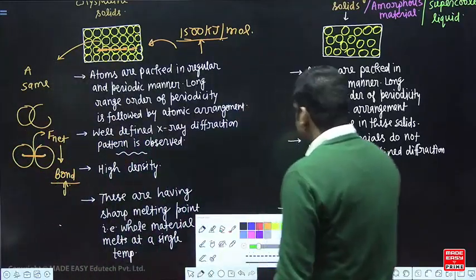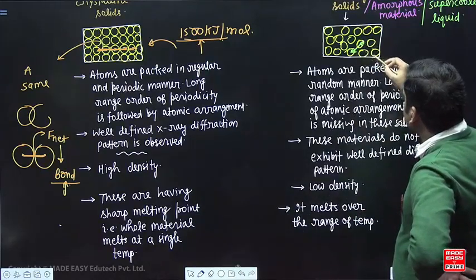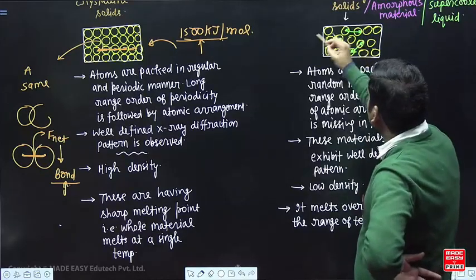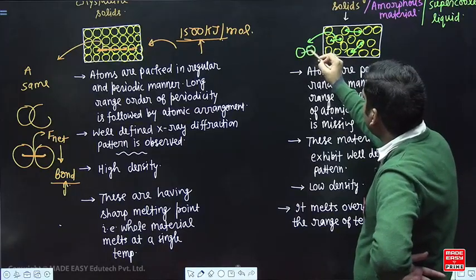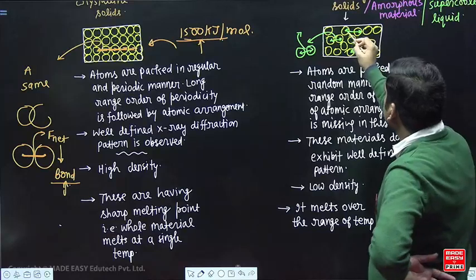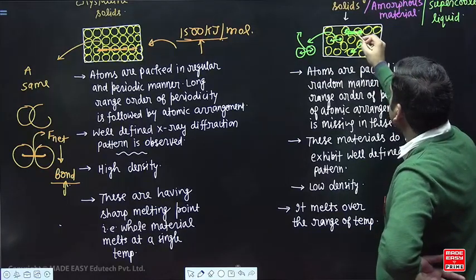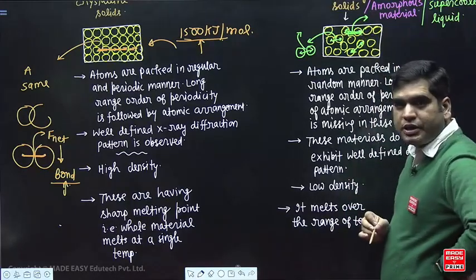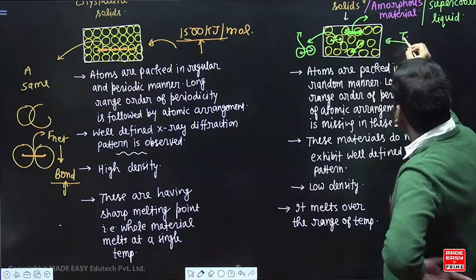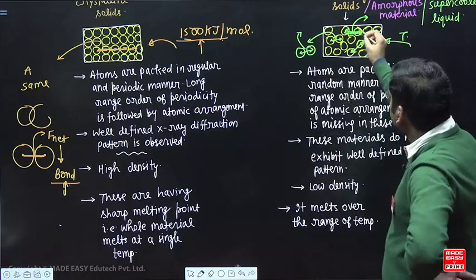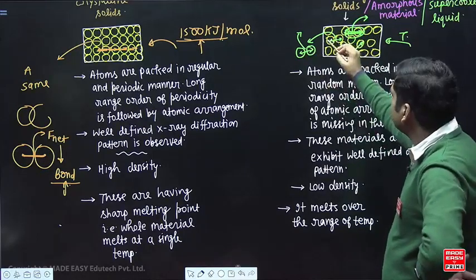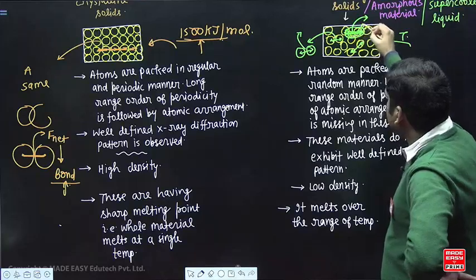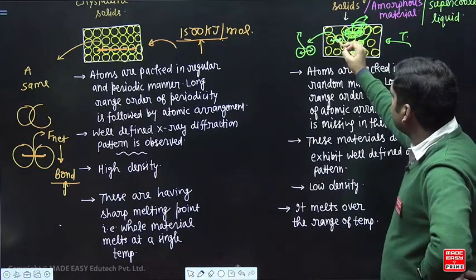In the non-crystalline materials, you can have variable interatomic spacing. Some atoms can be very close and some atoms can be far away. If the atoms are very close, then interatomic spacing is less and hence the bond is strong. But if atoms are far away, then interatomic spacing is large, and the bond is weak, right? So suppose I start to increase the temperature, then thermal energy will start to increase. The bonds which are relatively weaker, not exactly 1500 kilojoules, but 1490 kilojoule, 1480 kilojoule, this bond will first break.